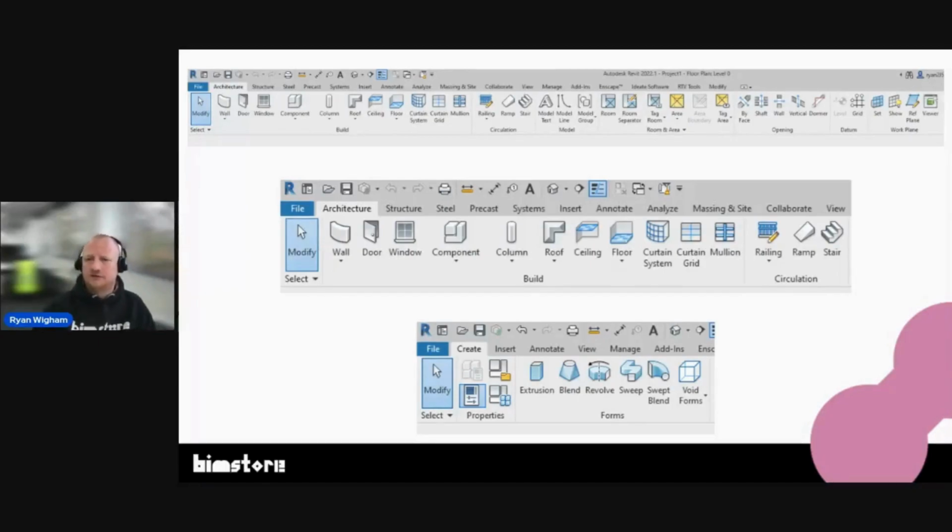And what Revit will do is it'll come with predetermined types, and you can adjust them to suit your needs depending on what you do, if you change that floor build up or a wall cavity size, whatever it is. Your toolbars will look different between the two environments. So you have the project, which I've just shown there, that's like a .rvt, and then a loadable family, which is separate to the actual project that you load in.